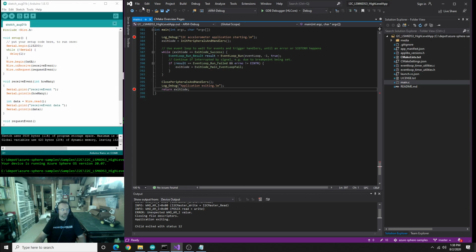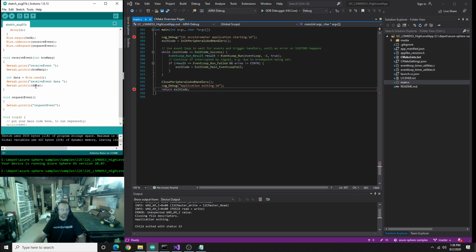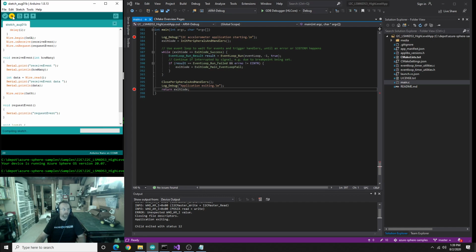Great. So what's next? Next, let's go ahead and actually reply back with the data that we wanted to. So we will do a Wire.write of the expected value, 69 that they're looking for in hex. So let's save that and upload.